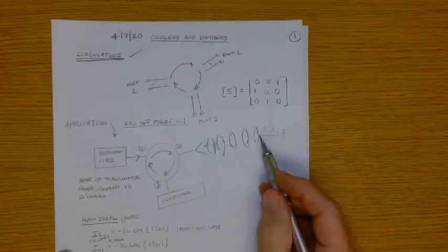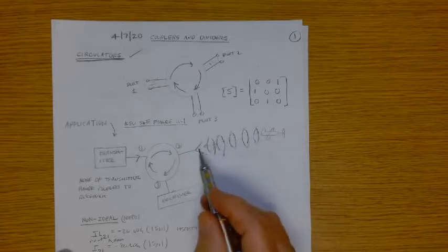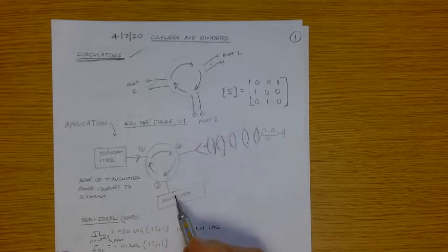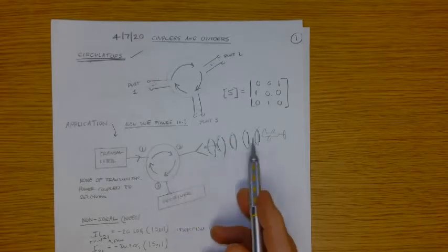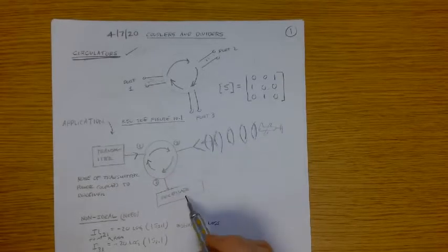This might be a radar application, and so the incident wave reflects off of the target and comes back into the antenna, and then the return signal into the antenna is, because of the circulator, all fed into port three, where our receiver resides. So we're taking the return from the target and processing it in the receiver to determine the Doppler effect, and therefore range or whatever other parameter we're interested in, etc.